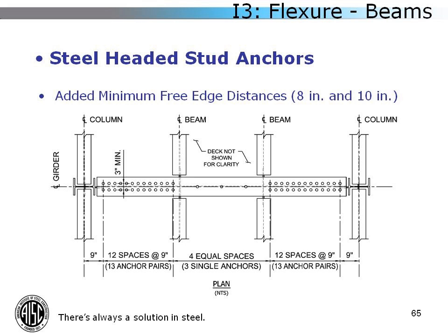So for instance, if you have a girder, such as shown on the screen, this is not a free edge. You have a column that's going to keep the concrete from breaking out between this last row of studs and the edge of the building. And even if this was just a regular steel member, you most likely have a bent plate along the edge of the building that you can also use your engineering judgment to say will prevent that concrete from breaking out. So this is really only applicable to formed edges, probably not going to happen a lot within your standard designs.